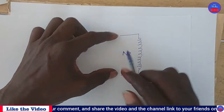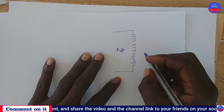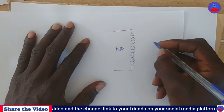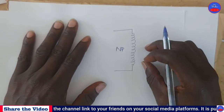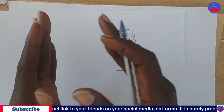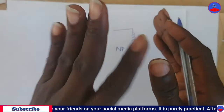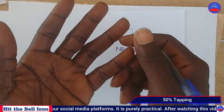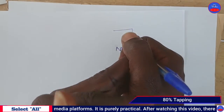We obtain the secondary windings by tappings on the primary winding. On autotransformer starters, we have three main tappings: 50%, 65%, and then 80%.